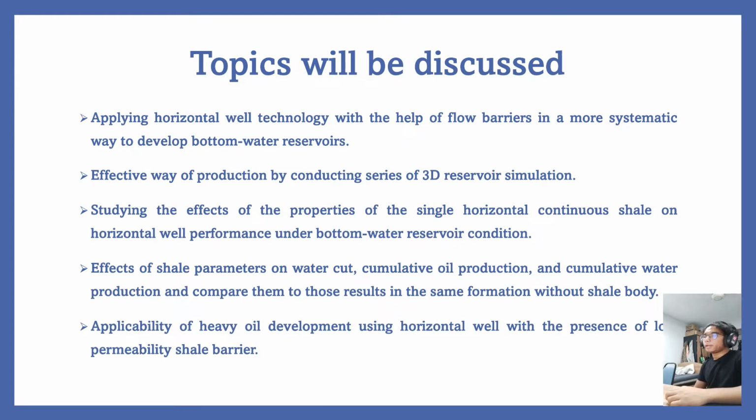The third is studying the effects of the properties of a single horizontal continuous shale on horizontal well performance under bottom water reservoir conditions. Next, finding the effects of shale parameters on water cut, cumulative oil production and cumulative water production, and comparing them to the results in the same formation without the shale body. And the last one, finding the applicability of heavy oil development using horizontal wells with the presence of low permeability shale barriers. That's all from me. Thank you.